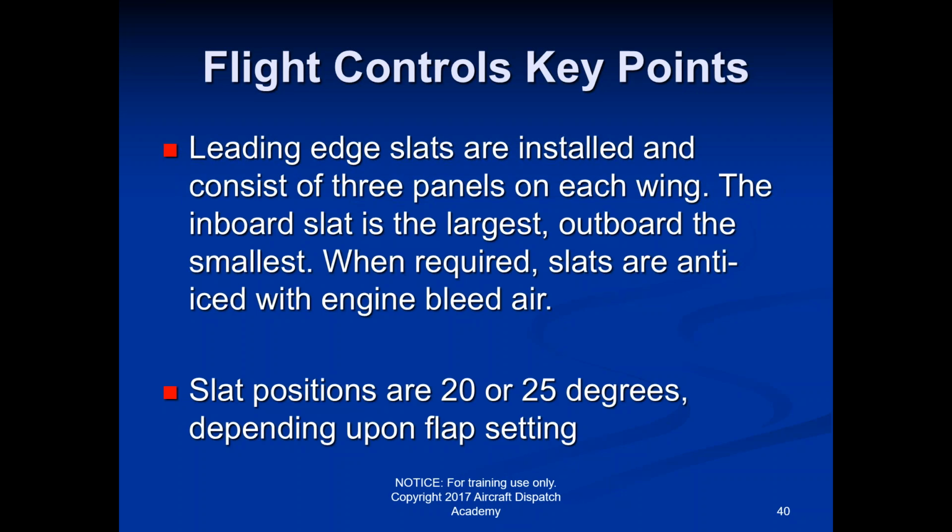The 200, like I said, if you're flying a lot in the 200, you never see it because it doesn't have slats. You only see the flaps, but pretty much any other aircraft has slats on the front, which basically do the same thing as the flaps. The only difference is they're going on the front and they're going down. If you remember the normal shape of the wing, the flaps will go down and elongate the back part and dip lower. Well, the slats do the exact same thing on the front. They just push down like this.